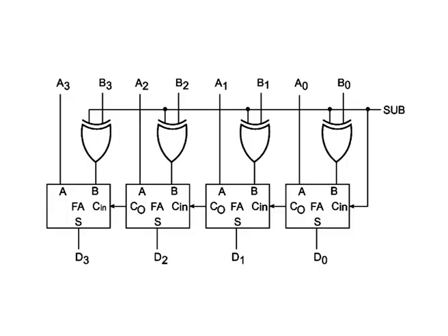Full adders can be used to perform subtraction provided we have the necessary additional hardware to generate 2's complement of the subtrahend and disregard the final carry or overflow. Figure shows one such hardware arrangement.